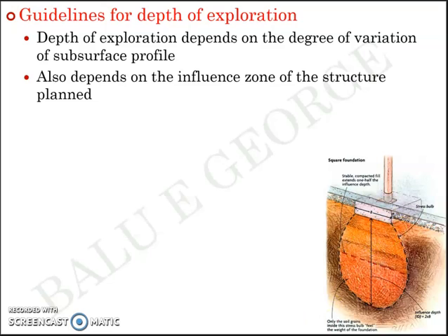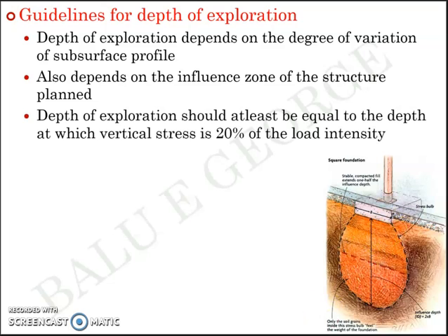So the depth of exploration should at least be equal to the depth at which the vertical stress is 20% of the load intensity. Again, these are just the guidelines. The decision solely rests on the engineer at site and also at the design office. So everything involves an engineering judgment. It's nothing like a codal practice that we follow, but still it involves engineering judgment, and the design engineer and the site engineer should have the actual practical knowledge on how to carry out the depth of exploration.